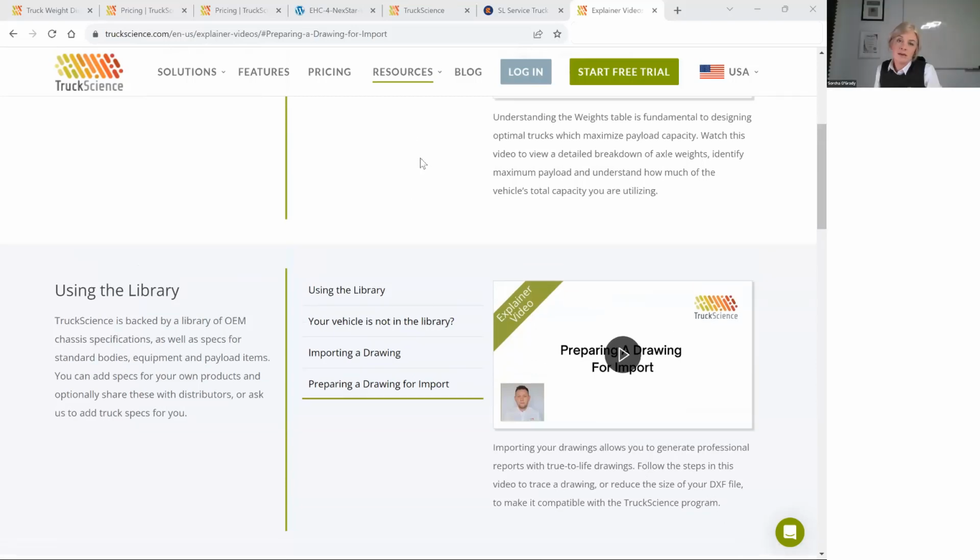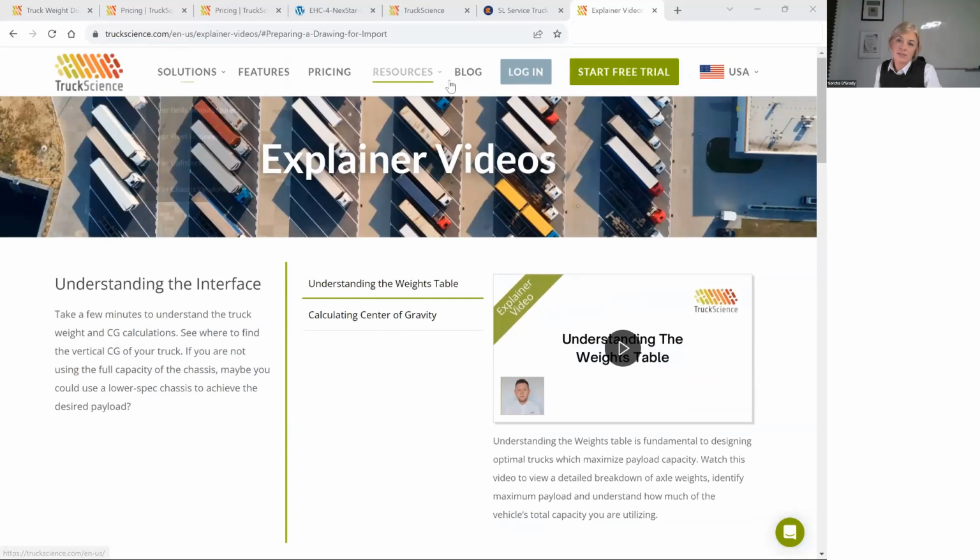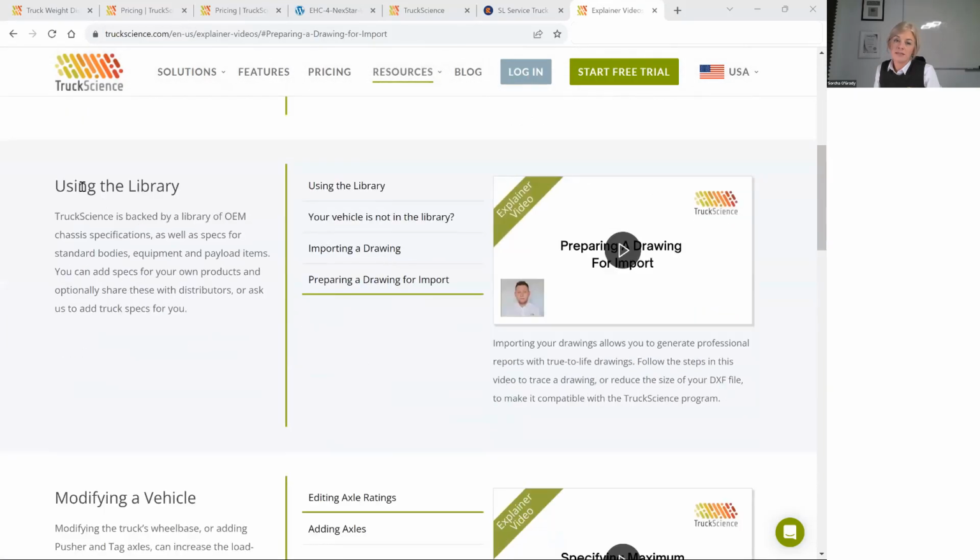Okay, so as Ian said, on the Truck Science website, there is a resources area here with explainer videos. These videos are all between 2, 3, 4 minutes long. And there is a section here on using the library, importing a drawing, and preparing a drawing for import. That 2 or 3 minute video will take you through the process of using, say, a PDF file and creating a DXF file by tracing over the PDF.